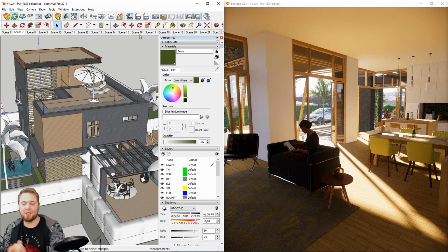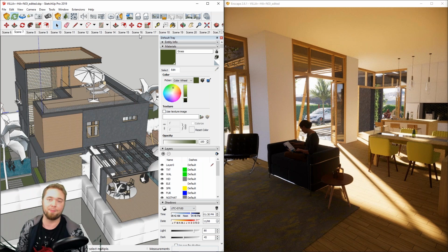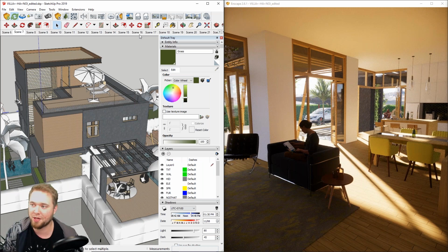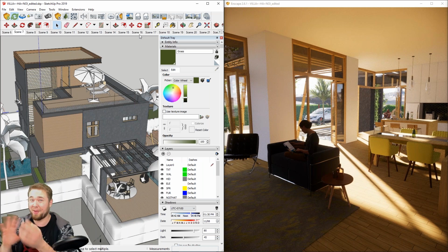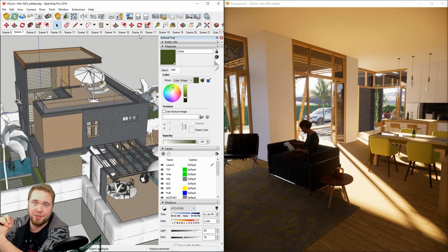our SketchUp users to achieve the same quality of results as our Revit users were achieving back in the days when we were only supporting SketchUp and Revit, we came up with a naming system that read your material name, and if you had some keywords in it like water or ceramic or metal, Enscape would adjust your display so it looks like that material. By now we've moved past that system, so whenever you see some naming conventions about Enscape, you can still use them, but it's not necessary.